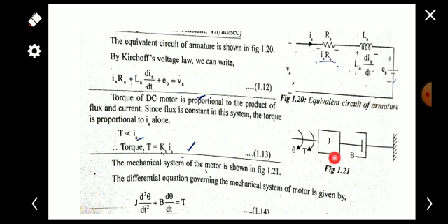For our DC motor, J, the moment of inertia, the mass element, is there and the dashpot is there, but here we can't see the spring, because for electrical machines we consider the effect of elastic deformation as very small, so we are neglecting that element.